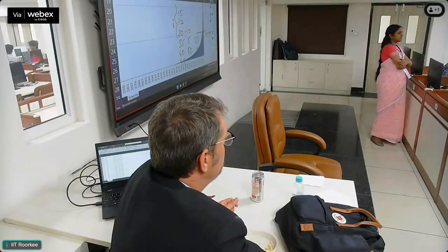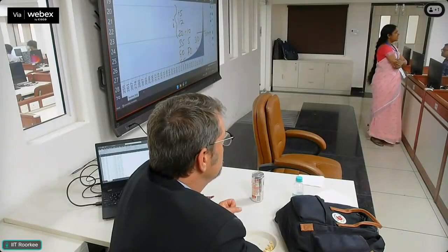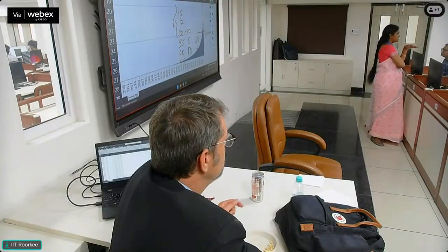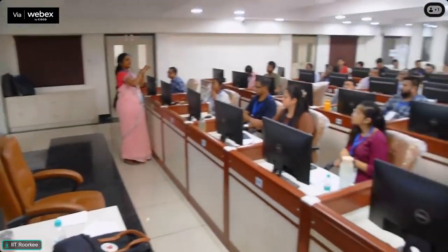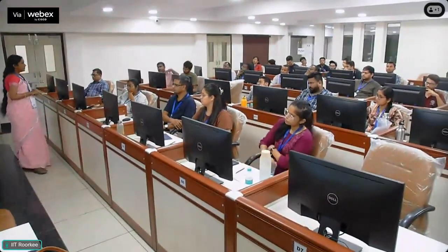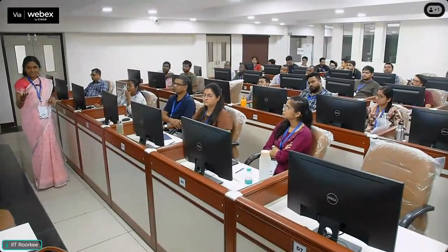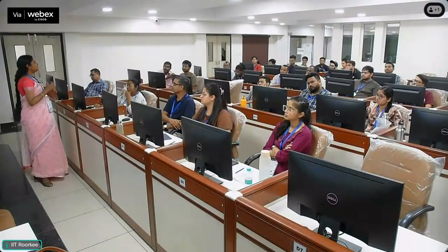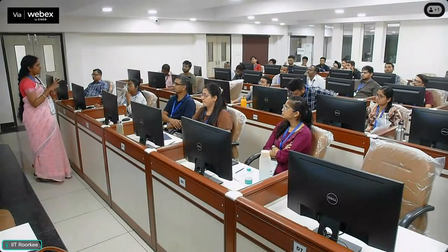The first flush will carry a high amount of pollutants, so we want to capture all the smaller storms. Even in the bigger storms, we are just taking that starting amount of precipitation. Generally they model with 17 mm. But when we use that 17, we found it is capturing only 60%.